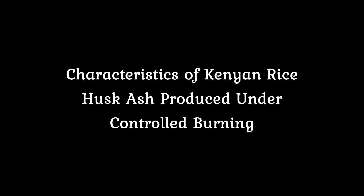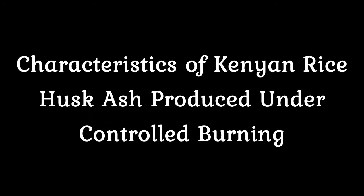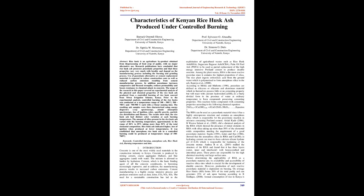Characteristics of Kenyan rice husk ash produced under controlled burning. Abstract: Rice husk is an agriculture byproduct obtained from the processing of the food crop paddy, with no major alternative use. Research publications have concluded that rice husk ash possesses pozzolanic properties and that these properties vary very much with locality and depend on the manufacturing process, including the burning and grinding process.